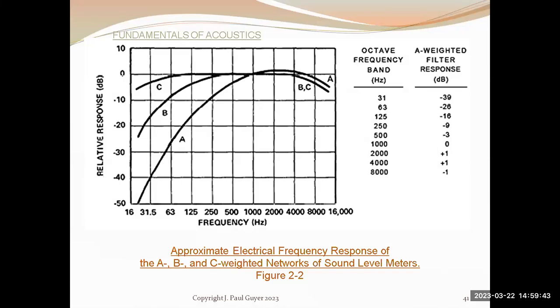And then the sampling rate, the fast slow knob, you'll set on the slow sampling rate, because on the fast sampling rate, the needle on the sound level meter is going to be unreadable. So that's what you're doing now.